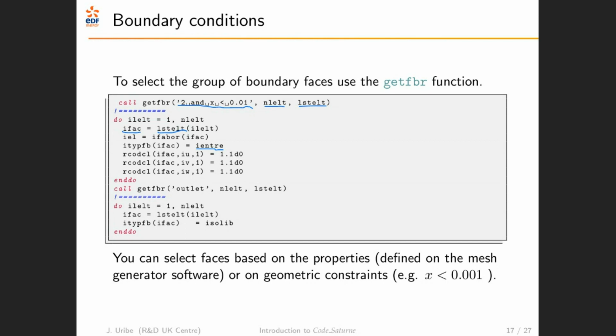Saturne creates volumes and creates cell centers, computing the center of whatever type of cell it is, and computes faces, creates the faces, and creates a face center, and then numbers all of these things that are created. So the face number is what would correspond to the mesh face that you would see in a normal mesh, but the actual mesh file doesn't have a face number. These numbers are created by Saturne.